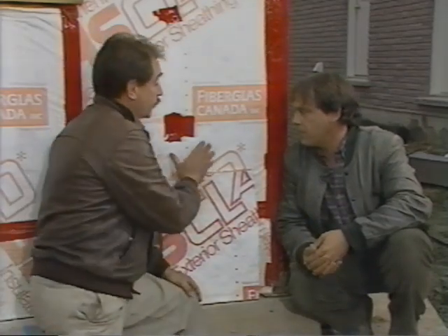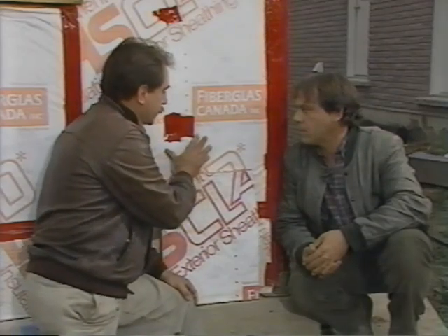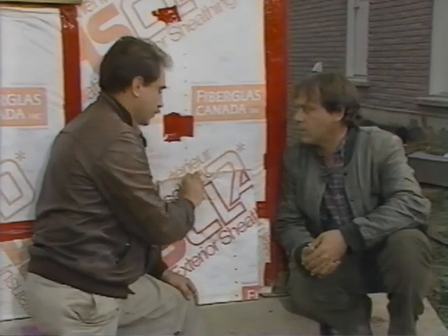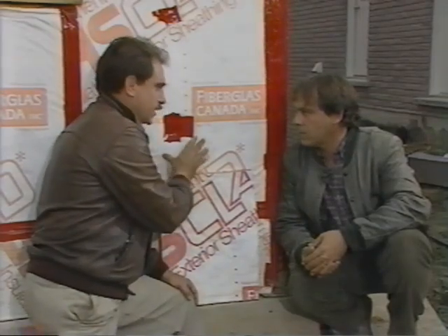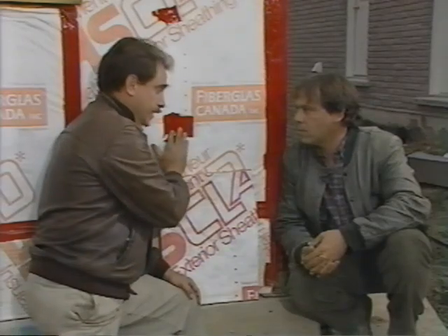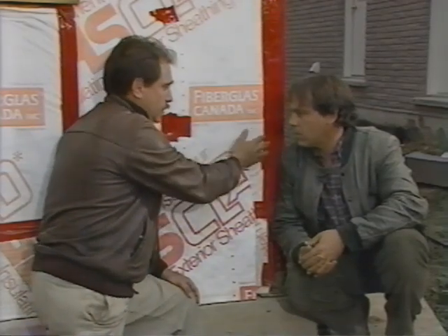Well, I brought you out here to see this paper. Now, this paper is not here just so that the manufacturer of this material can print his name on it. The purpose of this stuff is to act as a wind barrier, which is why it's been very carefully taped at holes and joints at corners and so forth. But it does breathe. It permits water vapor to exit from the wall cavity, so if any gets in there, it can breathe to the outside.